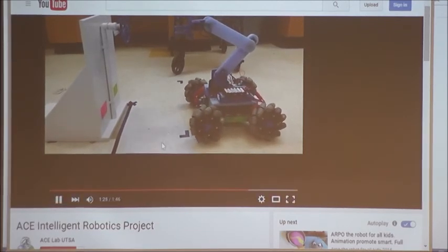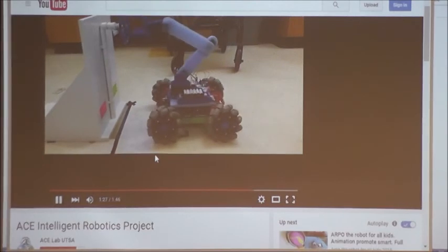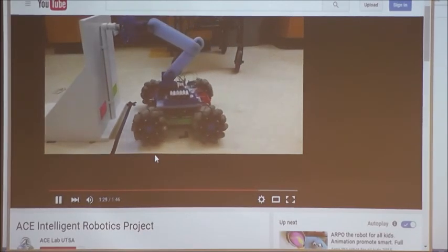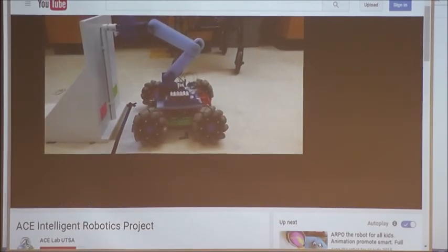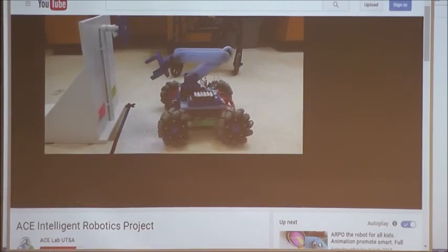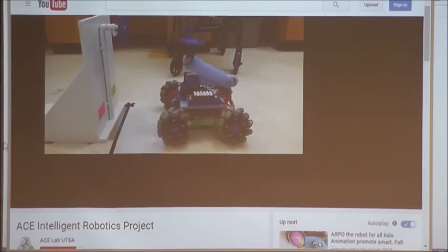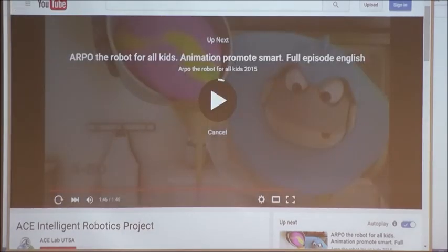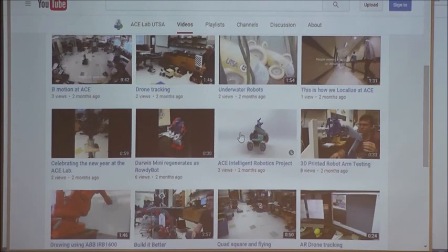Yeah, the camera. It has a camera in front, so it calibrates itself based on the color tags you see at the bottom, pink and green. So it calibrates its heading angle. So the robot can understand, okay, I'm lined up with the valve, so I can use the manipulator. The end effector looks like the valve, so it can turn it on and off.